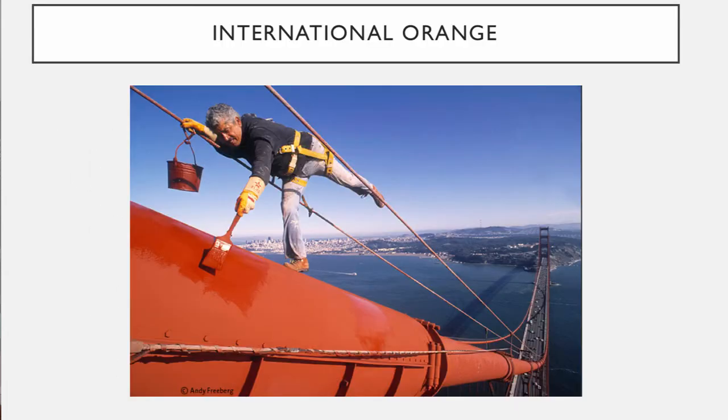All right, so painting. We talked about painting, and here we are painting the Golden Gate Bridge. If you were not aware of this, the Golden Gate Bridge is being painted just darn near every single day of the year. It's a continual process. We move from end to end of the bridge. What they actually do is they will build up in certain areas protective barriers to protect the workers and also to protect the drivers on the bridge, and they will sandblast. They will do things to get a lot of the pits out of the steel if they have to, local repairs. Then they come back with a primer, and it turns out they use a primer that is filled with zinc to act as that sacrificial layer.